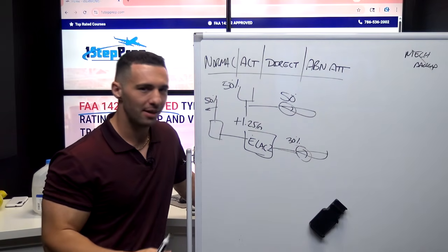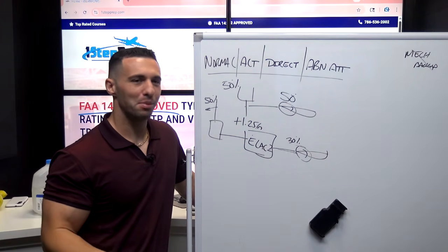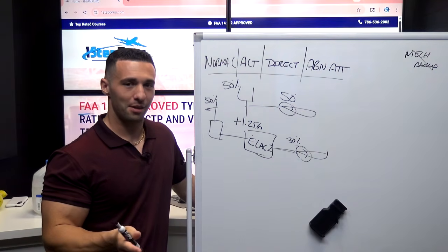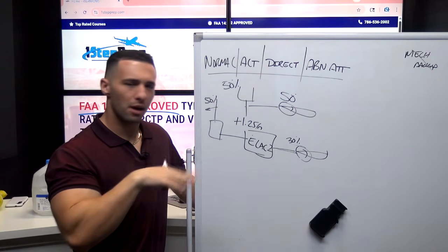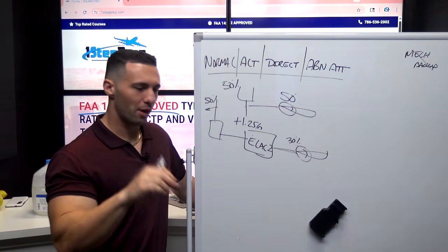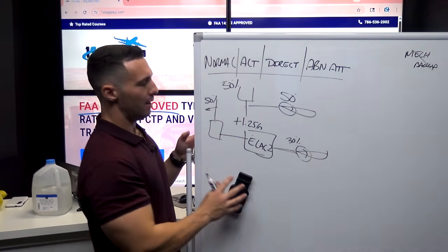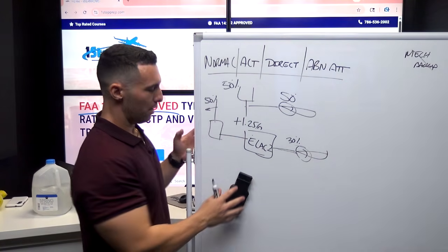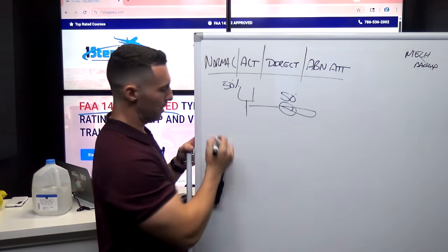And all of this, by the way, I just want to share with you, can very much be demonstrated and validated in an airplane, or better yet in a sim. I'm not saying go do this in the plane, but you could certainly get in the sim and just go level flight, 5,000 feet, turn off all the automation, autopilot, everything, auto thrust, grab the thrust levers and just go to TOGA. Now, what you would expect in any other airplane is for the nose to very dramatically come up.